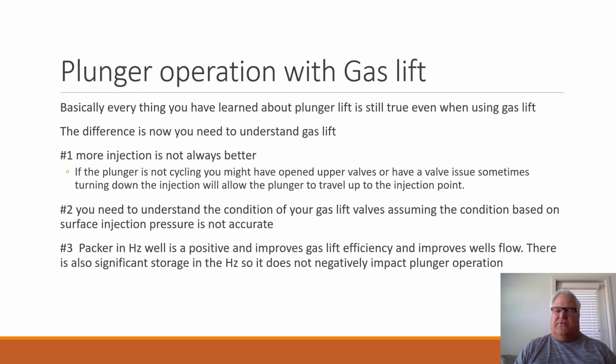So you don't get this extra where the liquid is slamming past the end of the tubing and then dropping back in and slamming back up, and it really can make quite a big difference. Packers in horizontal wells, very positive, especially if you can get them landed down around that 65 degrees or near the end of tubing, makes a big improvement.